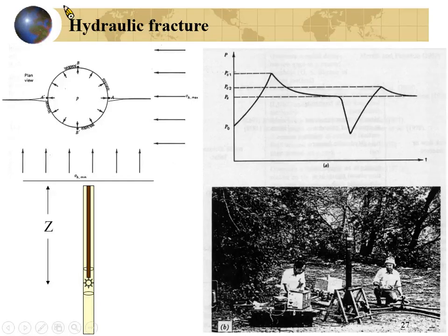After this, we inject pressure into the borehole and measure the pressure rising and decreasing. We increase the flow pressure from the hydrostatic pressure, because you have water within the borehole, the groundwater table, so you already have a pressure in the segment.